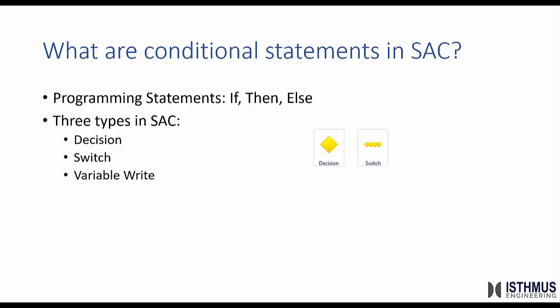One thing to note with these is that as your corridor is building, it checks these conditionals at every frequency point. So as your corridor is going through and building every 25 feet, or whatever you've set your build rate to, it checks, am I above or below existing ground now? Continues with the conditional, builds what it needs to, and then at the next frequency point, it resets and starts over. That's really what gives it the flexibility and dynamic nature as the corridor is building. But just be aware that it does run through these conditionals every single frequency point along the corridor. It's not an issue in terms of time or processing power, but we do need to be aware that it gets reset and run every single frequency point.